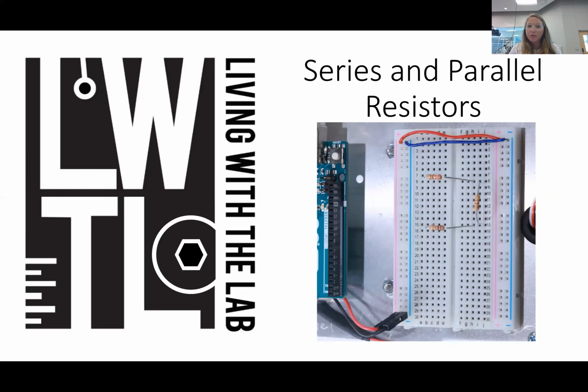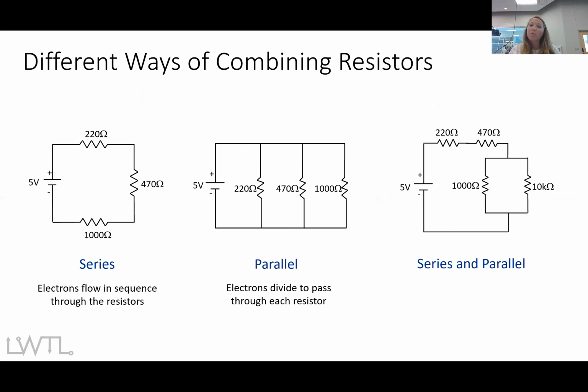Now that you know how to build circuits on your breadboard, let's talk about different ways to configure circuits on your breadboard. So you have multiple resistors, and sometimes you might configure them in different ways on your breadboard. So you might have what we call series circuits or parallel circuits or a combination of both. So if you have series resistors, basically you have one resistor right after the other.